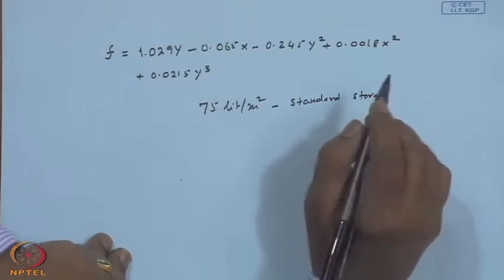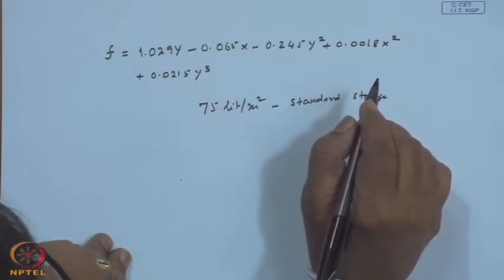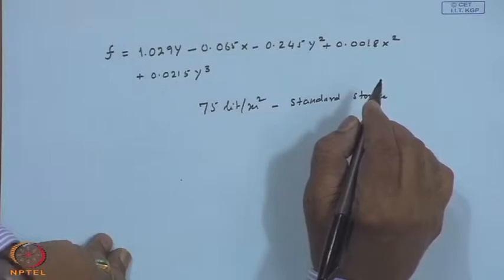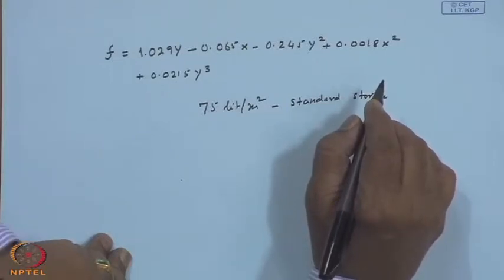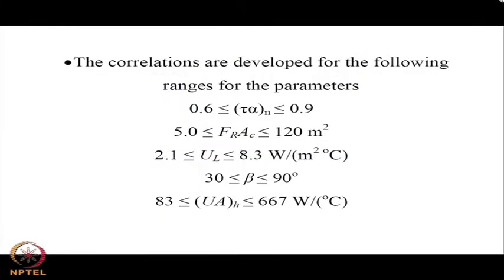So, apart from the pressure drop and the pumping power requirements, for a given x and y, it appears that they will give more or less the same solar load fraction. But the real question is, will the air collector and the water collector have similar FR-UL and FR-tau alpha for a given cost. In general, liquid systems have better values of these two parameters that characterize a collector, FR-UL and FR-tau alpha. So, the ranges of the parameters are the same.